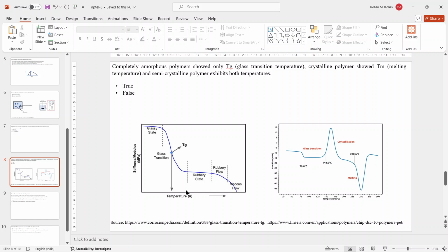Next, we have the crystalline polymers. Since the crystalline nature of the polymer is much higher than its amorphous one, the polymer chains are arranged in proper spherulites and lamella structures. Now, what are spherulites and lamella? Lamella are zigzag structures which are quite ordered, and they are formed because the polymer chains and the secondary forces are actively arranging them into a certain close packing structure.